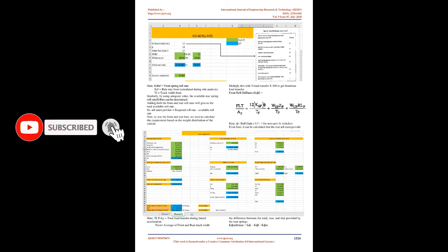Here, KFSF equals front spring roll rate. KRF equals ride rate front, calculated during ride analysis. TF equals track width front. Similarly, by using the adequate values, the available rear spring roll rate, KFSR, can be determined. Adding both the front and rear roll rates will give us the total available roll rate. So, the ARB must provide the required roll rate minus the available roll rate.